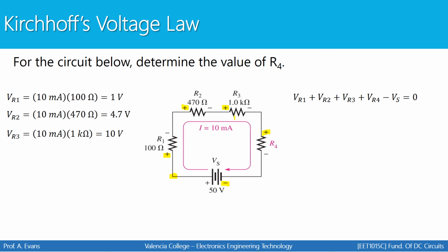When I sum up all the voltages around a closed path, you start from this point, write down each voltage you encounter until you get back to where you started, and just include the polarity. Whatever sign you hit first is the polarity, positive or negative. So KVL says that if I take a point along a closed path and write a sum of every voltage drop along that path, it has to equal 0.